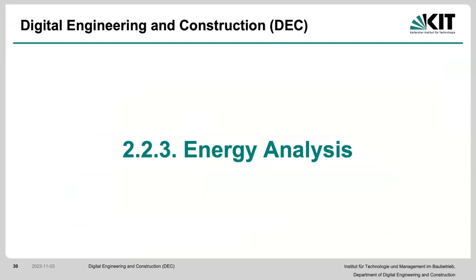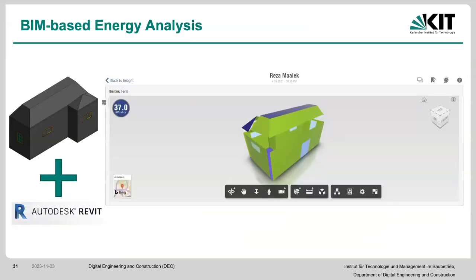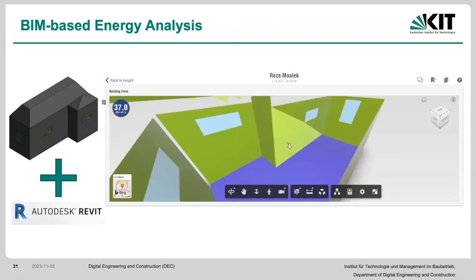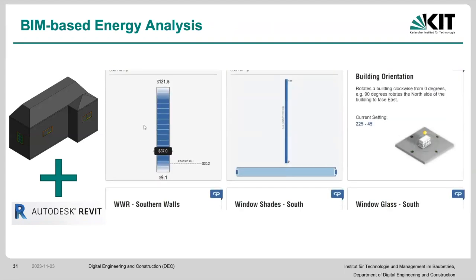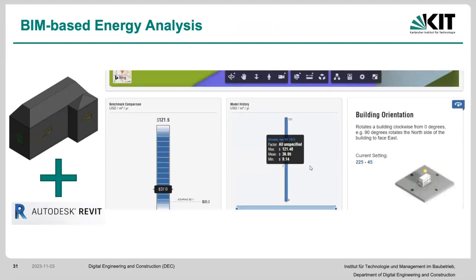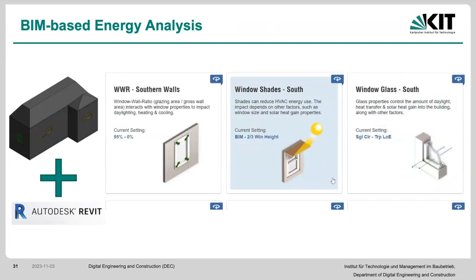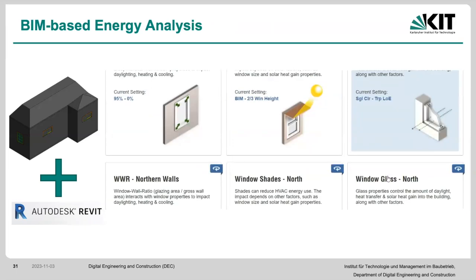Okay. Energy analysis. Again, we have built-in software through Revit. You would be able to do that, and it would do a cloud-based analysis. Again, the level to which we can rely on this information also becomes important. However, if we have that, we would be able to do a few different types of analysis, and we would be able to know, let's say, how much the yearly usage is based on, let's say, the average household cost for energy. You can get some average number there. Again, this is average. If you want to get a better idea about it, it has to be more local. You have to know exactly what the variations of the market are going to be, and so on and so forth.